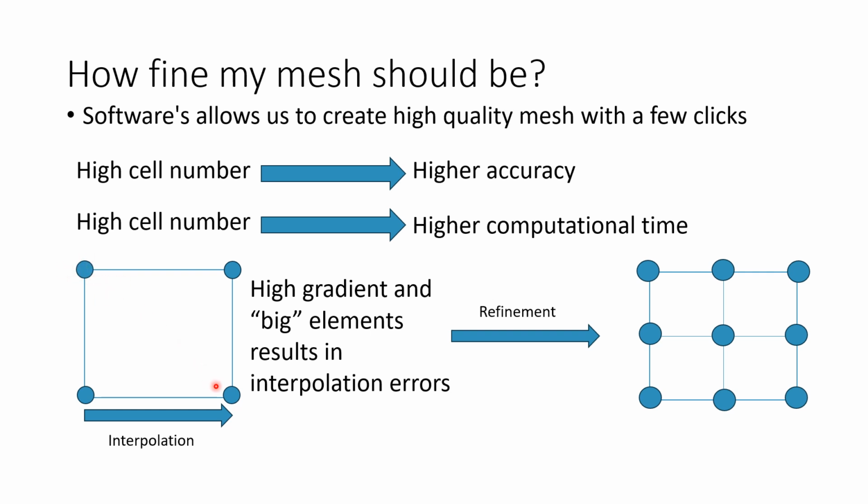Basically, it operates by making an interpolation between two nodes and then calculating the things that it needs to. I think everyone understands now why it can be a problematic area if the mesh resolution is not enough. The interpolation will be enormous when our forces or stresses are very high, which is basically a huge magnitude.